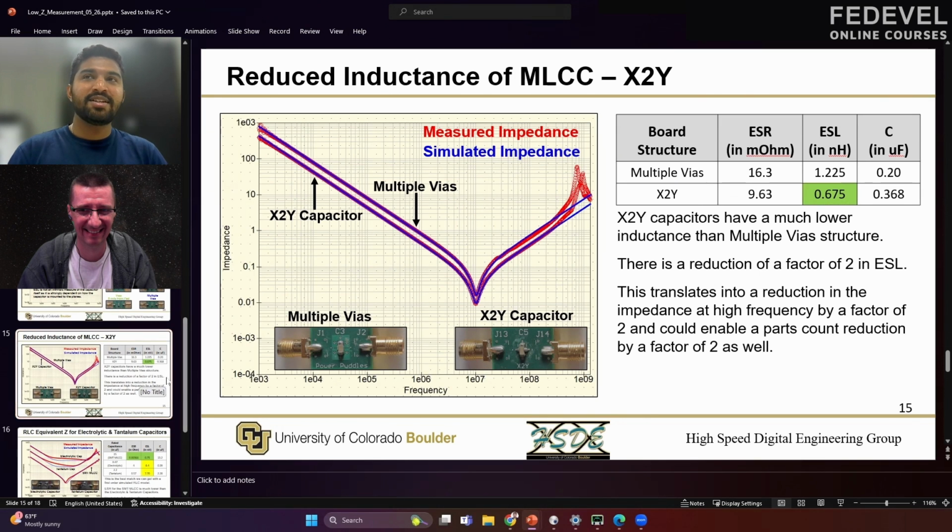This presentation is majorly about the 2-port measurement method using the low-cost VNA, but I also wanted our audience to walk away with some principles that would help them design or analyze PDNs later. This is very important to see, because this will show everyone differences between different components. It's not like a 10 microfarad capacitor is the same for everything. There are differences between different kinds of 10 microfarad capacitors.